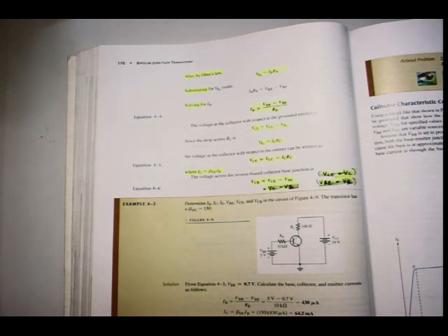VCE, and in this specific circuit's case, VCE and VC will be the same thing because there's no resistor at the emitter, so there's no voltage drop. It's going to be the supply, VCC, minus VRC, the voltage drop over RC, Ohm's law, IC times RC. But I can also use Kirchhoff's law. We actually did use Kirchhoff's law. And then the voltage at the collector with respect to the emitter, VCE, which is actually the same as VC, is VCC minus ICRC, which is the volt drop over RC.